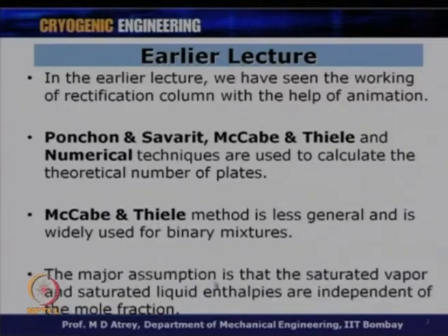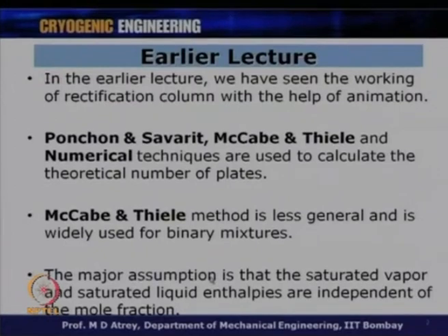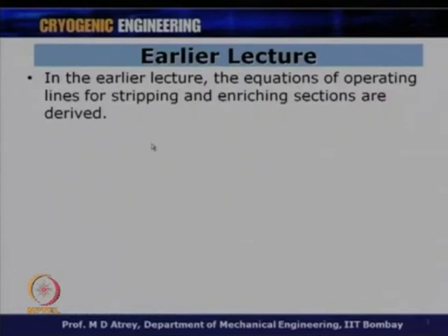The major assumption is that the saturated vapor and saturated liquid enthalpies are independent of mole fraction. So, we assume here that the capital H and the small h, which are the enthalpy of the saturated vapor and saturated liquid, are independent of molar composition. This is what we have seen in the earlier lecture in detail.